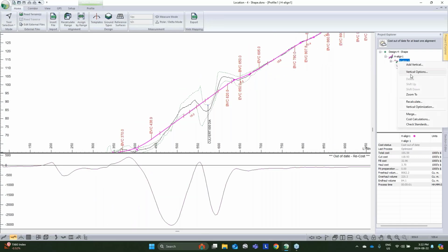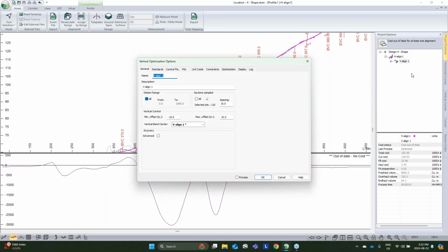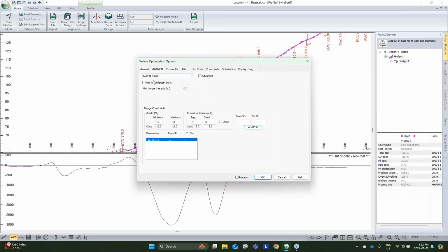The other aspect of controlling our alignment shape that's worth talking about is the solutions other than just this fast curves option. There are a few options here. With polylines, you don't get any curves, it's just individual polylines. With user defined, you could click in where you'd like your curves, and the software will move those up and down to get the best vertical alignment with the assigned curves. But here we'll talk about variable curves and tangents.